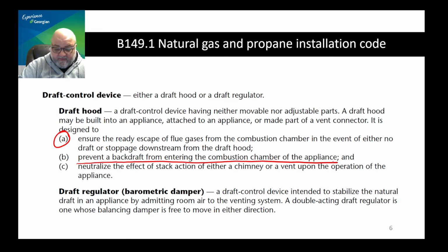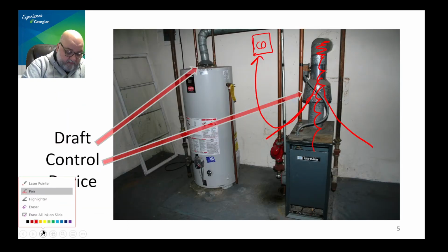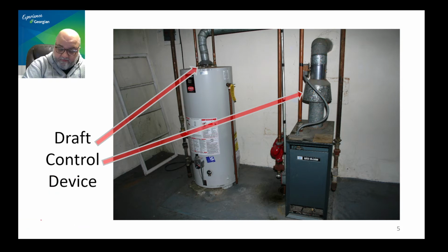Well, it is very similar to what we just talked about. If you are operating properly, however, the draft, the flue gases, are pushed back down instead of being allowed to go to the atmosphere. And we're going to see that there are two possibilities for that to happen. If they are pushed back down, you don't want that to fall in the combustion chamber.